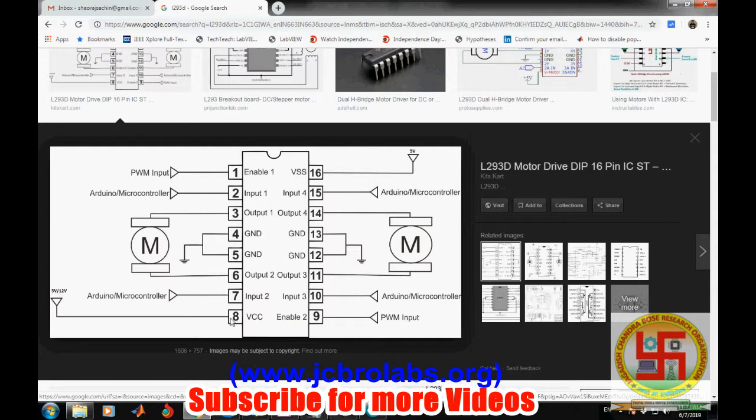So this L293D is a 16-pin IC, right? Pin number 1 and pin number 9 are the enable pins. It has two ports, one on this side and one on this side. Pin number 1 enables this particular port, and pin number 9 enables this other port. So we need to connect pin number 1 to 5 volt and pin number 9 to 5 volt. Pin number 16 provides 5 volt to the IC, and pin number 8 is connected to the 12 volt power supply. So 12 volt is connected here.